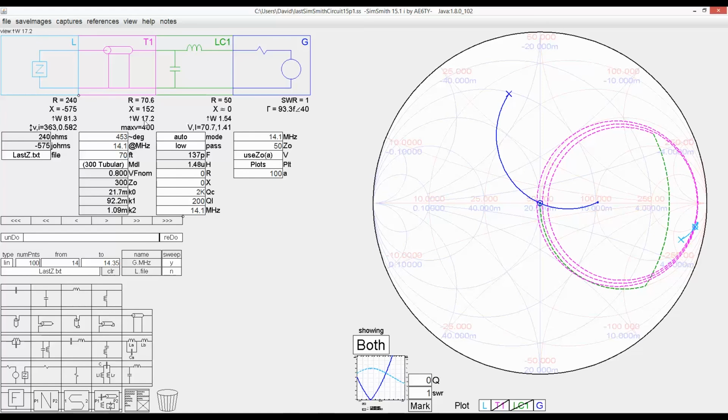We lose 17 watts, at 20 meters anyway, in the transmission line and end up with 80 watts. Really, between this and the 450 ohm ladder line, I doubt you'd hear any difference. These differences are really not going to be perceptible.